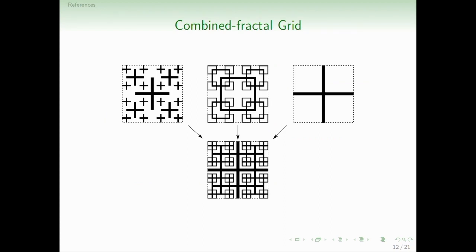So I tried to design what might be a more suitable grid and produce better homogeneity. And by combining two fractal grids here, left and right, plus the cross here on the right, which means that there's an obstruction behind the center line for each of the four grids, we can sort of push the solidity out, and hopefully the jets, which are persistent in the corners, will be broken up by smaller bars up here.